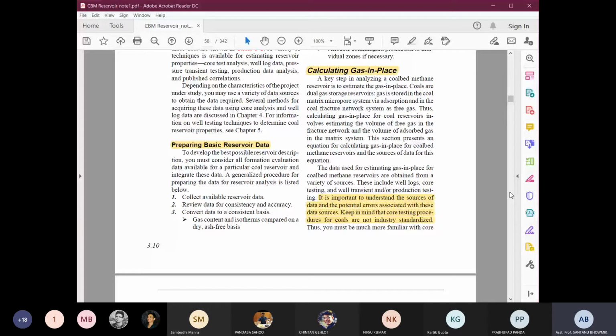So all of them may not be following the same procedure. There may be differences in the concept, and differences in the standards they follow. So in that case, there are also some chances of uncertainty. And when you compare single borehole data across two or three different companies, obviously there is a mismatch. Why? Because the standards are different. So that much error you need to consider.